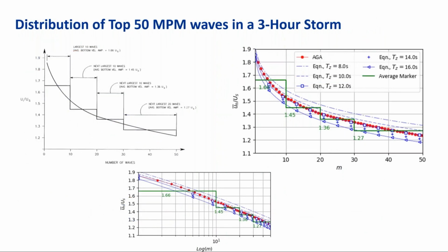And this is for the storm. Again, the top left frame is from the manual, and on the right hand side is where our work shows that these coefficients that are multiplied to US are validated against extreme value analysis methodology. Details of these discussions are in the OMAE paper in 2018, and you can find the formulation and the descriptions in this regard. Next one, please.